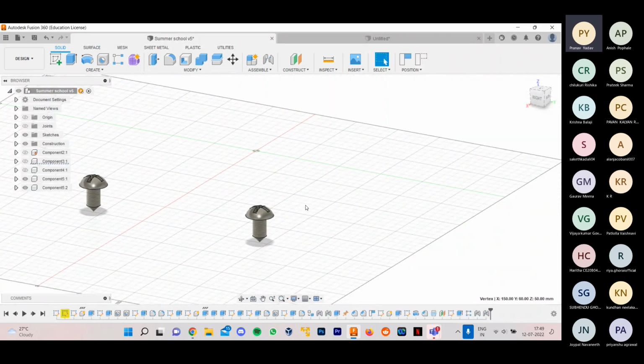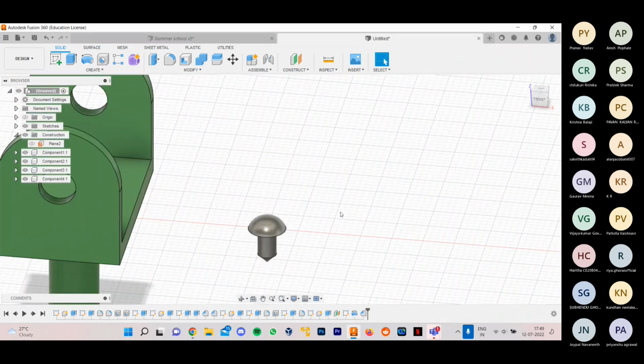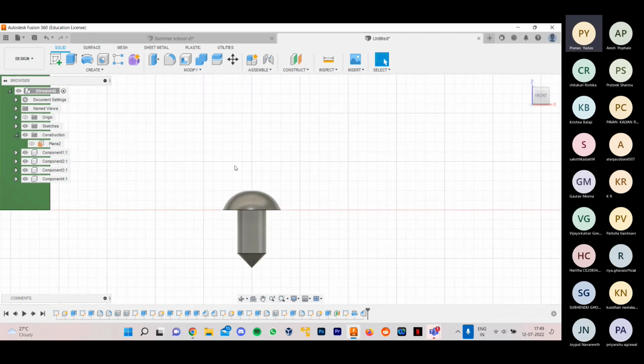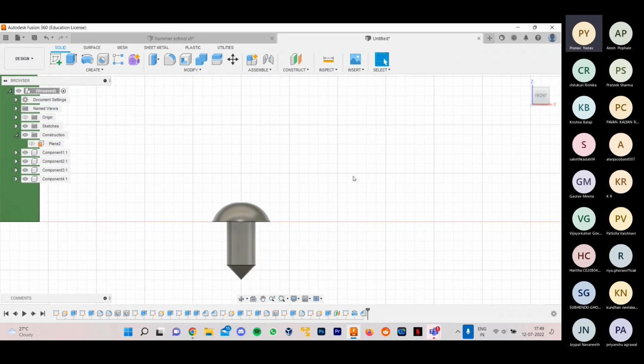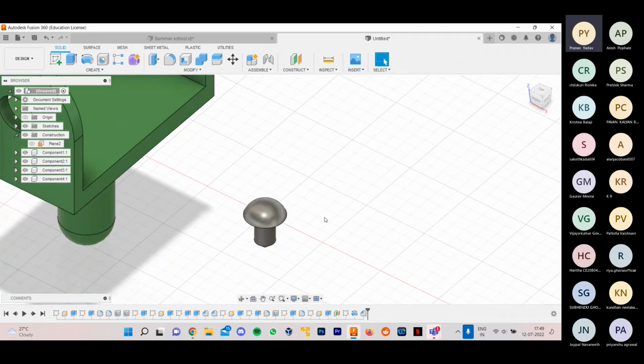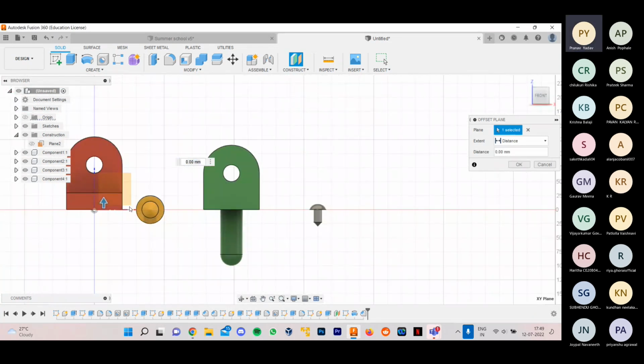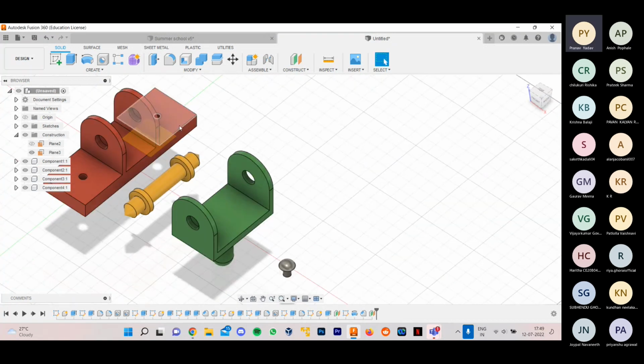be here as well. So the next thing I would say is I want a plane here at the top. The plane should be, I think, here horizontally, so that I can make a plus and extrude it inward so that I can cut a plus through it. So let me offset a plane. I'll choose this horizontal plane and make it go through some, I think this is pretty good. Okay, so we have a plane here.